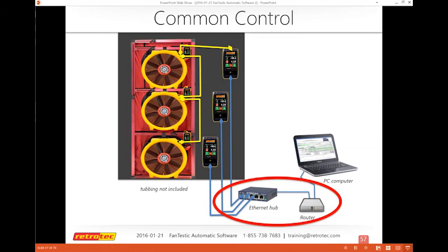I wanted to make a point down at the bottom, for those of you still learning this, that I could have 2 gauges, 10 gauges, 25 gauges, and I need to have them all put into an Ethernet hub. You can have multiple hubs that all ultimately go into the router. The router determines the network assignment to each of the gauges. No matter how many gauges you've got, the router says this one gets this number, this one gets that number. They're all assigned, and then your computer with the software can control all the different gauges because they've all been assigned a network number.